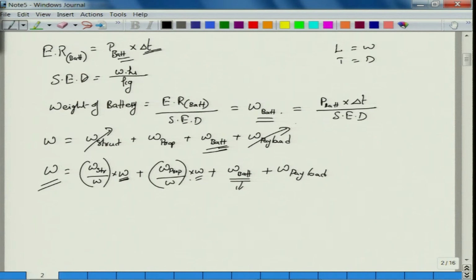So, the power required for us from these two equations is thrust required times velocity of flight, is not it. So, that is nothing but drag times V infinity. Or say if you divide these two equations, what you have is thrust required upon W, T by W is equals to D by L, or say thrust required is W upon L by D.